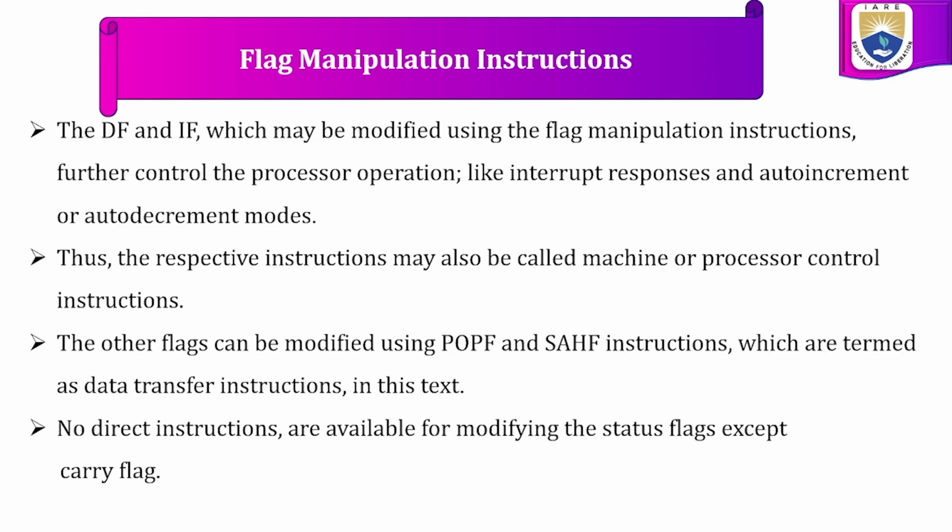The direction flag and interrupt flag, which may be modified using flag manipulation instructions, further control processor operations like interrupt responses and auto increment or auto decrement modes. Thus, the respective instructions may also be called machine or processor control instructions.